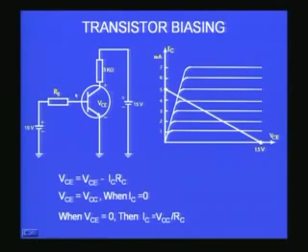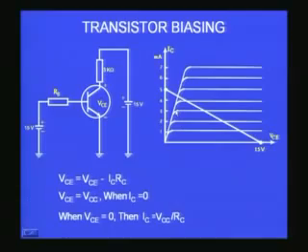In general, for different base currents, I will find myself somewhere along this line, and therefore this gives me the different operating points that I can choose for my transistor amplifier with this specific value of VCC and RC. If I change my RC, correspondingly the straight line also will change. Again, if I change my VCC, this will change. If I change both VCC and RC, the whole thing will change. Of course, if I change the transistor, the whole characteristics will have to be drawn again. It will be slightly different characteristics.